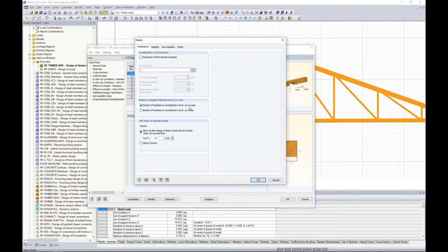What this is used for is for glulam beams. They sometimes have, or not sometimes, they always have different bending design values for our top versus our bottom in tension and whether our moment is positive or negative. So default in the program, the positive local axis for Z is pointing down for our members. So typically you won't be adjusting this unless you're rearranging the local axes of your members. So that's just what that is in reference to for our glulam beams.